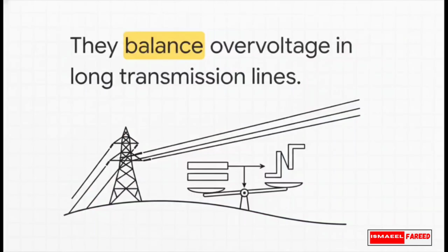Now, scale this way up. On a massive industrial grid, if a transmission line acts too much like a capacitor because of its immense length, it can create very dangerous overvoltage. So we balance it out by adding shunt reactors. It proves that everything in electricity requires perfect opposition to function safely. If a system leans too far toward capacitance, we inject induction, and vice versa. It's just an elegant, continuous dance of physics.